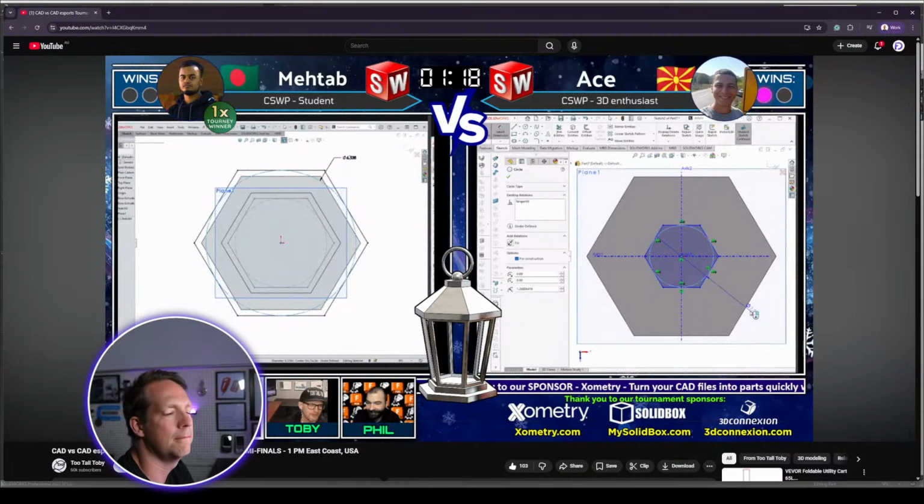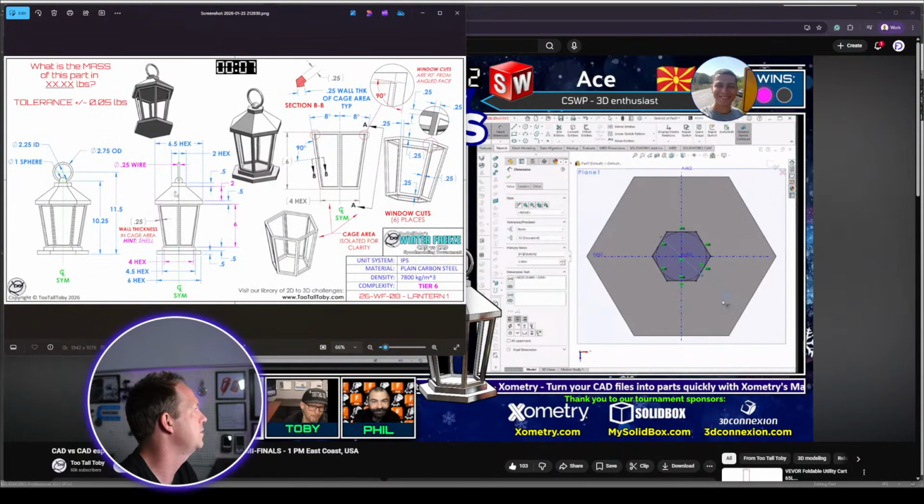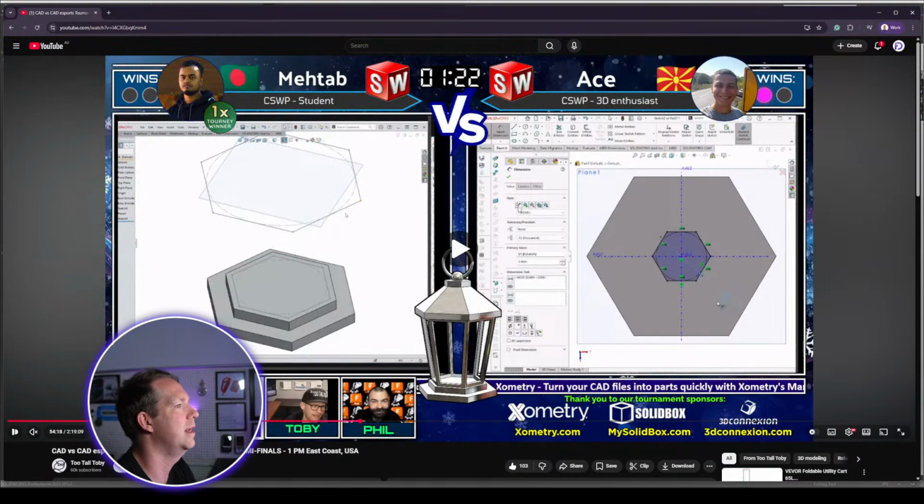I actually do a lot more modeling, or in my project work, I try to avoid creating new reference planes. Instead, generally, I'll use an offset feature in the sketch or in the extrude itself. Because in this one, like his offset here for this 6 millimeters, you don't need to offset. If you know the dimension, which you've got 4 hex here, and you know the angle, which is the 8 degrees, you can just draw your hex, extrude 6, draft angle 8 out, and that will work out that offset plane. You don't need to actually go ahead and create a plane there.